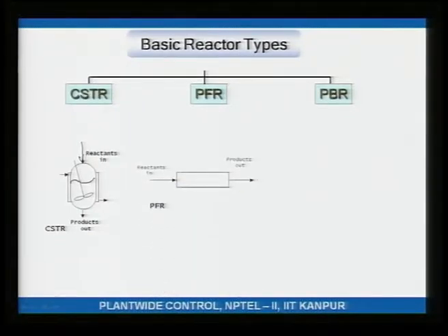A PFR, like I just said, is a hollow tube. You have material going in, and since that material is hot, inside the tube reaction occurs, and then you have whatever is going out. Typically what will happen is you will cool it, and once the reactants have been cooled, the reaction does not go any further. So, here there is reaction, at the exit there is a cooler, and because the hot reactor effluent is cooled, in this stream there is no reaction.